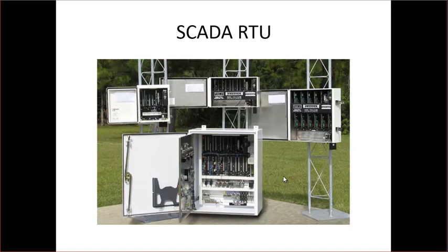This is a nice picture here of a SCADA RTU. So this is something you might find if you were to go out to an electric substation or anywhere out in the field where you were trying to make measurements and do things. You put the computer systems in these little weatherproof enclosures and close them up, and you have power running to them and a communications line running to them, and they sit out there and do their thing. So that's a SCADA RTU. I've seen RTU as remote terminal unit or remote telemetry unit. I like the acronym remote telemetry unit because, obviously, that's what it's doing: taking measurements and reporting data back.